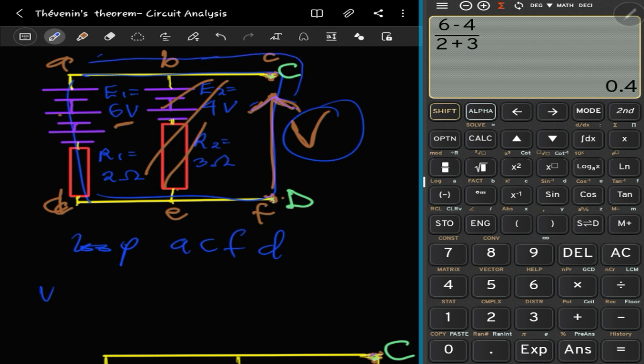If we are going this way, the next voltage source we will meet is this one, but we meet its positive terminal, so it's going this way. So to be in the opposite direction, which gives it what? -6. Now we use the loads, right?